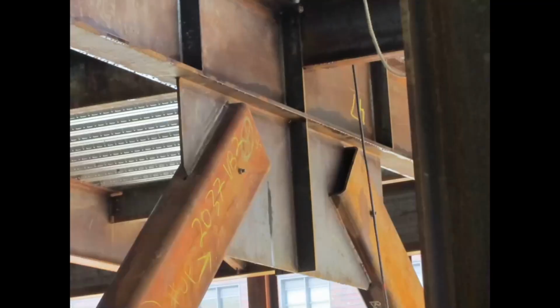We're also going to look at a special case today. We haven't talked very much about HSS as they pertain to tension members. And for the most part, it's because we don't really bolt them. They're kind of hard to bolt. They're tubes. You can't really bolt HSS sections very well. And the preference is to weld them.